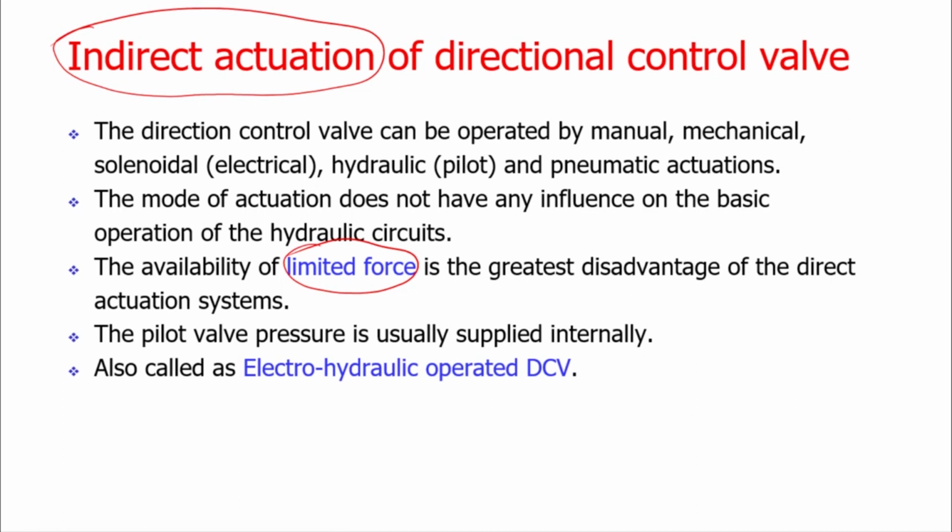So to operate such huge valves, we are using another valve. We are using a supplementary valve to operate this directional control valve. And this extra valve which is operating the directional control valve works based upon the electrical energy itself. So these are called electro-hydraulic operated DCVs.